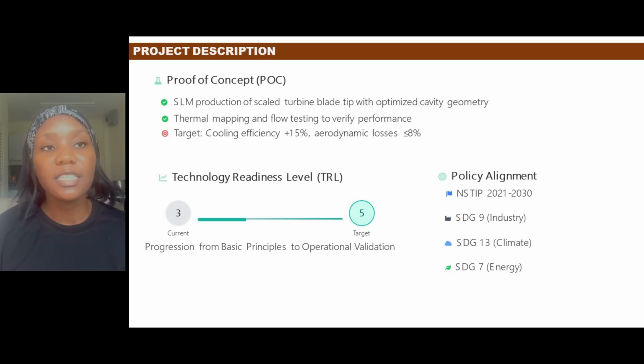So in this research, CFD is a central tool which is going to be used to analyze the complex flow and heat transfer phenomena occurring inside the turbine blade cavity, and it allows us to create a detailed physics-based numerical model of the fluid flow and temperature fields interacting with the blade geometry. So we are going to employ conjugate heat transfer simulations, which means that both the fluid flow in the cavity and the heat conduction through the blade material are modeled simultaneously.